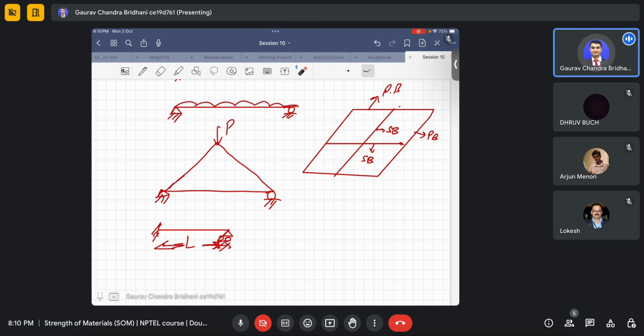One bearing will give movement only in one direction, meaning it will allow the structure to expand or stretch in one direction. Another will give you both directions. Some are called multi-axial bearings, so they will give you movement in all directions. They will have a very little tolerance, suppose 2 mm, so it will move 2 mm in both directions. So your design has to be appropriate so that it should not move beyond 2 mm. So things like that are there.